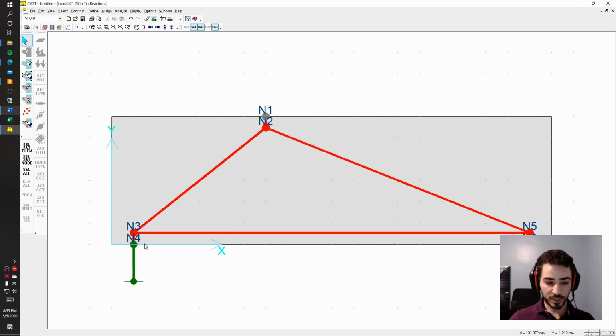And you can change the size of these elements by clicking on these arrows right here. The first arrow is the size of the font, such as N1 and N2. For example, if I click here, you see that it diminishes. The second one is the thickness of the nodes and the lines. I like it thick. And the load and support size, for example, this green restraint size, you can also adjust in here. So okay, so this is our first iteration.